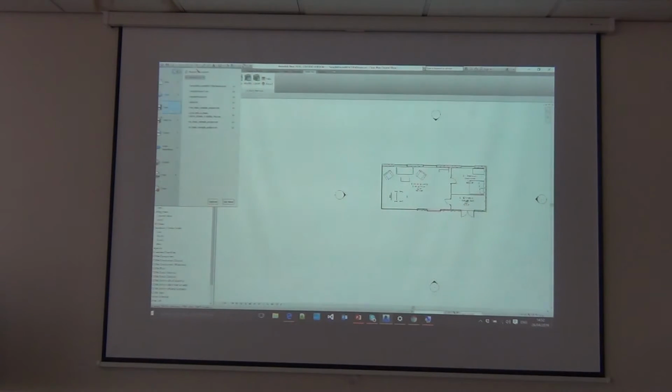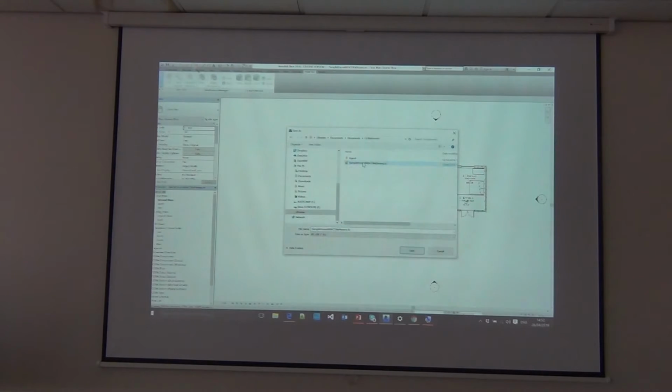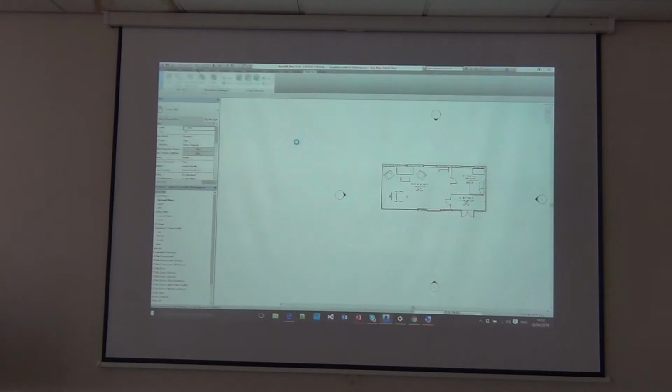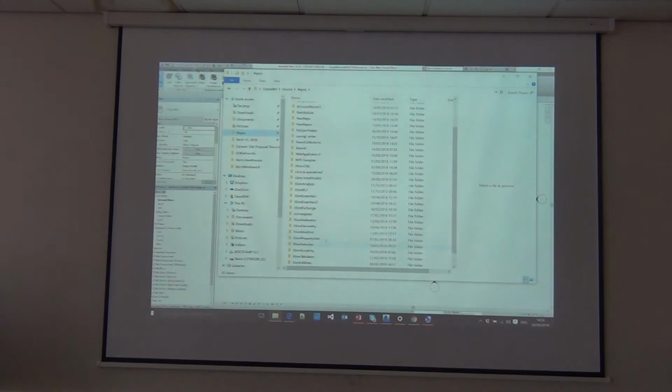So if I go to the IFC way of doing it first, so I'll go Export IFC, choose the FM handover view, all the settings are okay, and I export it, then what I will get is, I'll just overwrite this file. So this is creating an IFC view of the world now. Now once I've got that, I've opened up the number of tools I can work with this significantly. I can take it to another BIM tool if I want. I can take it to a whole pile of analysis tools and reporting tools. I'm just going to show you it in XBIM. So if I come here and just get the Windows UI for XBIM.